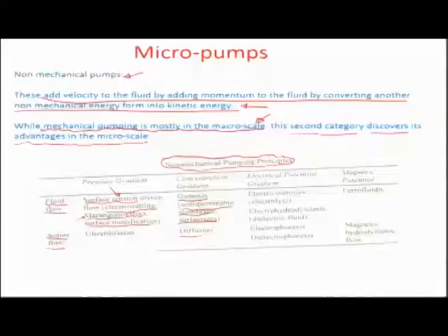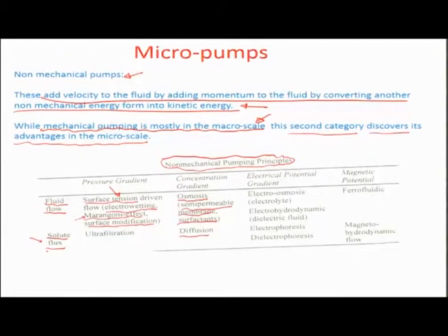So, if there is such a gradient across a membrane, there is almost always the possibility of mass transfer to happen, so that the concentrations on both sides may become equal. Again, there can be diffusion driven flux, where the physical molecules would move diffusively from the higher concentration side to the lower concentration side in a fluid path, and it would again create equality of concentration on both sides. So, the driving factor here is the concentration and a concentration gradient.